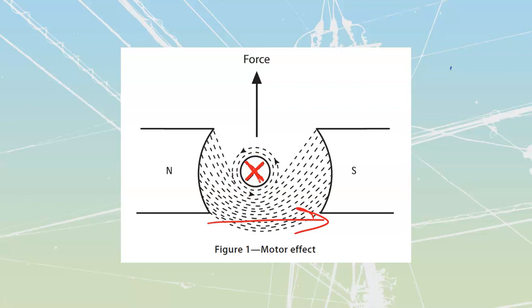It's the cross that we're seeing over here, which means I'm going to have my center finger pointing down and into the page. With your first finger going across from right to left, or from left to right, and your center finger going in, you can now unfold your thumb. You should see that your thumb aligns with this force. If it doesn't align with that, you're doing something wrong. It should align with that to push that out.